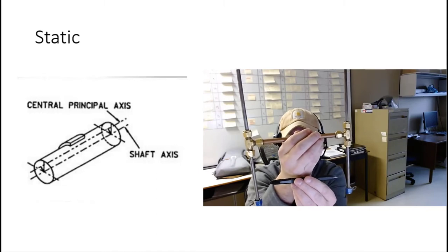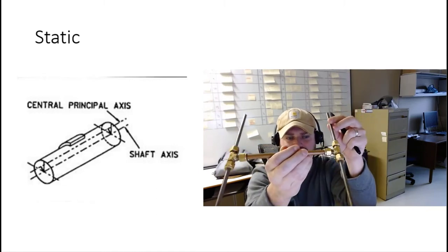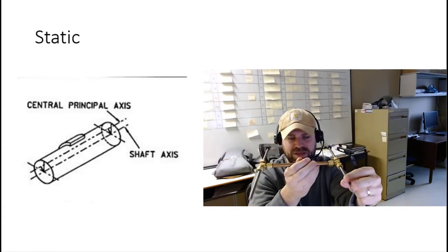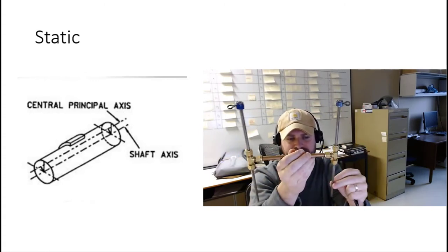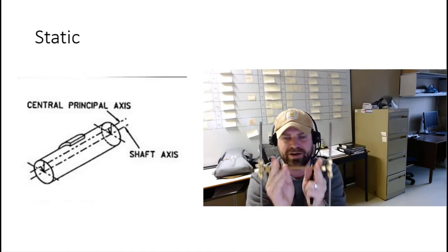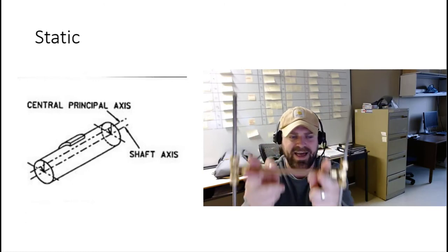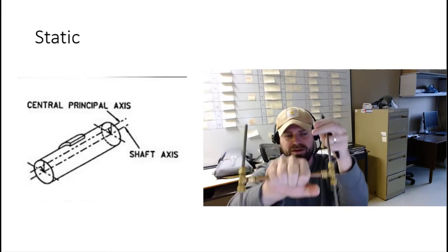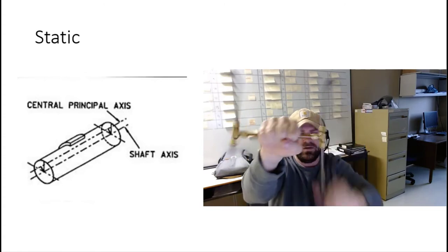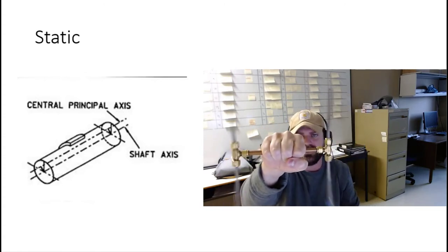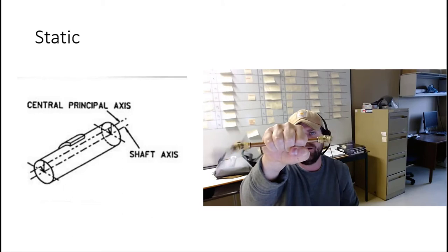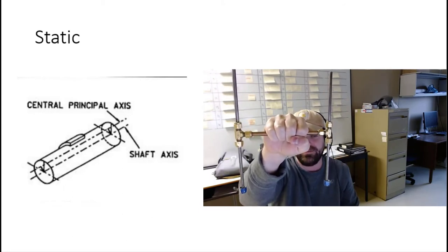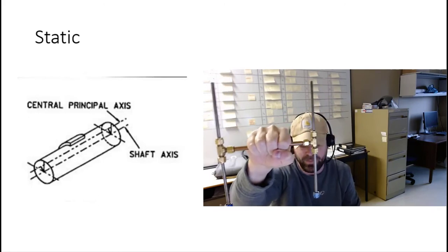When I spin this around, it wants to come towards you, and then it comes up and then towards me and then down. So those bearings are going to both equally have that weight distribution loaded and applied to it all the way around. I'll give one more spin just to show. And then it nicely falls and sits down at the bottom and lands. And that is static unbalance.